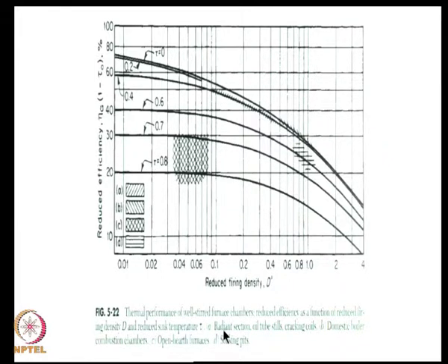For example, A is this region, it is the radiant section of cracking coils and oil tube stills used in refineries. B is the domestic boiler, which is used in many houses in cold countries to heat the houses. C is open hearth furnace used in metallurgy, this is this region, and finally, soaking pits also used in metallurgical applications right here. So, 4 different kinds of furnaces here are all represented in a single chart,